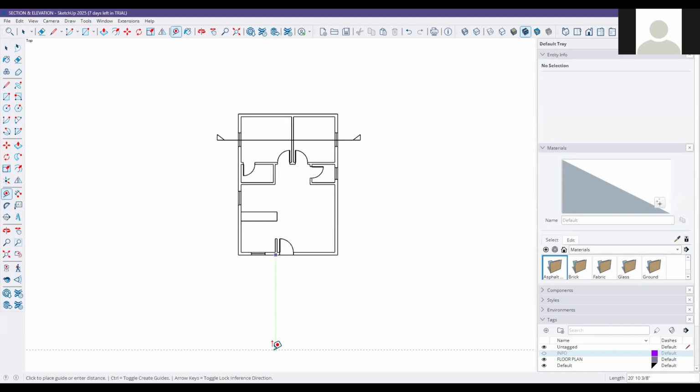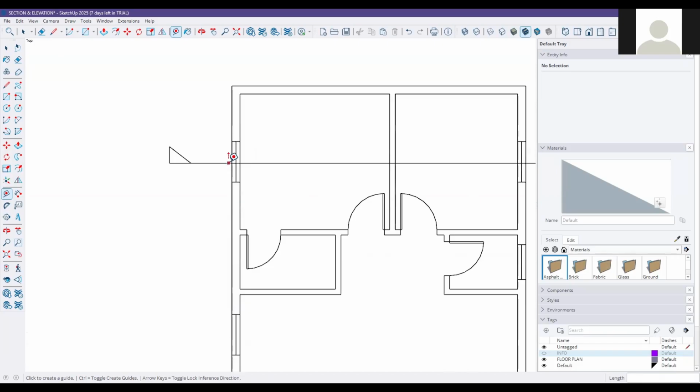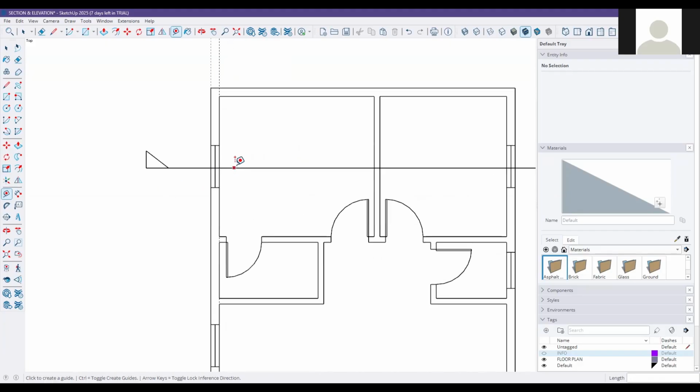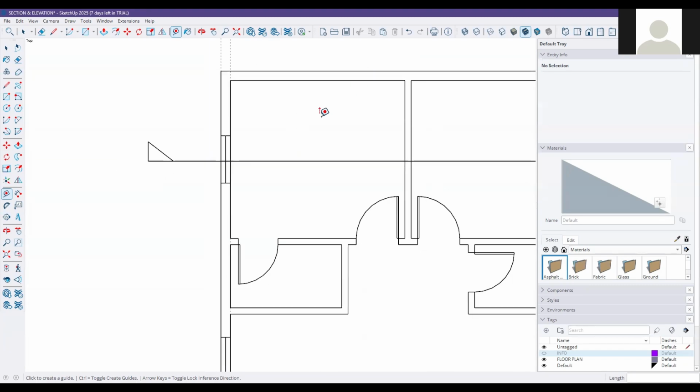I'm going to drag one line from here to here, where we have this section line. Here we have one section line, so I'm going to grab and drag one line here and leave it there. Again, we have the next lines, and here we have to drag one line and leave it there. You'll see a face of this elevation is the interior walls.